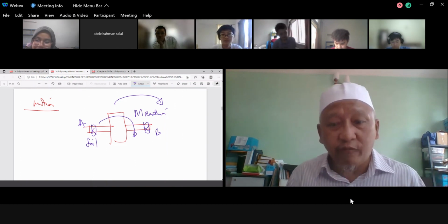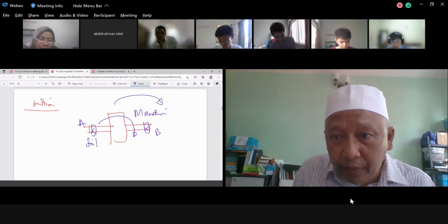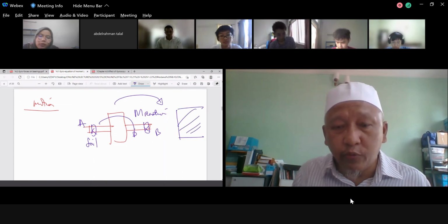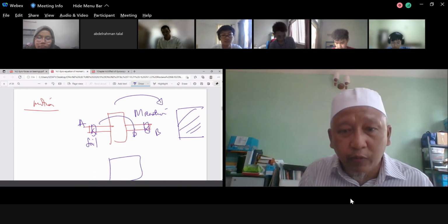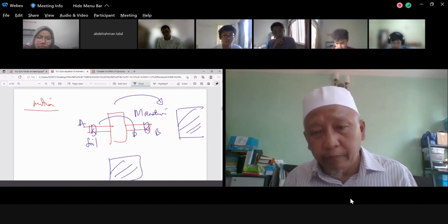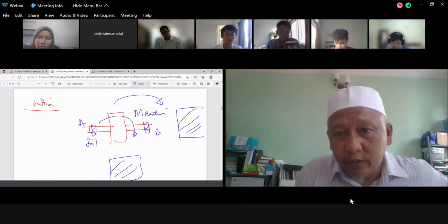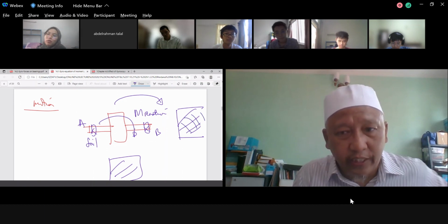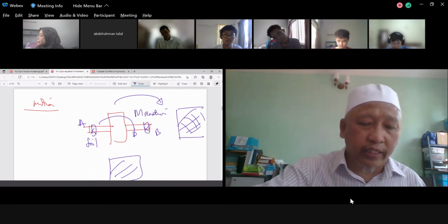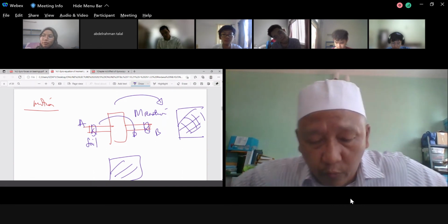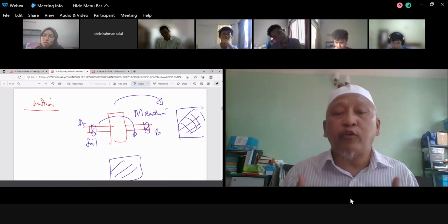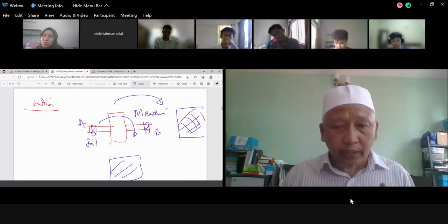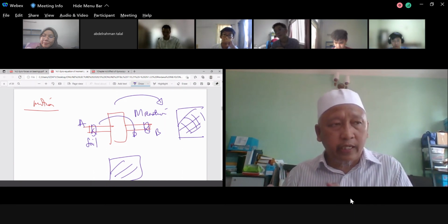So if you are an engineer, for example, if you build a control room here, it's very dangerous, right? You cannot build this one. You have to build in front of it because it will provide security to the personnel. Otherwise, if this one fails, it will hit your control panel or operator. So this is the possibility an engineer must consider when you design something. It is not only up to the force. You also have to think about where to build the control room, where the operator sits, where the operator's workplace is, and so on.